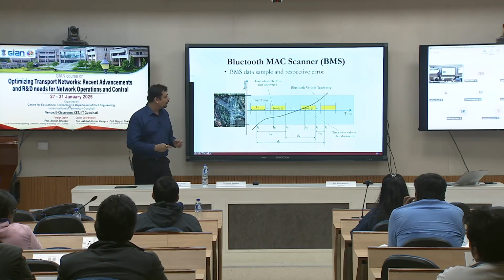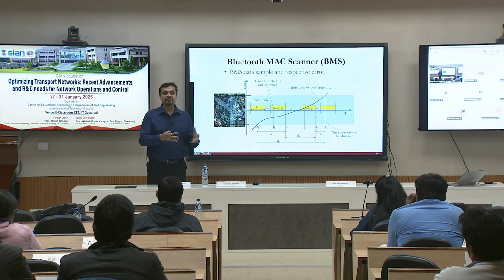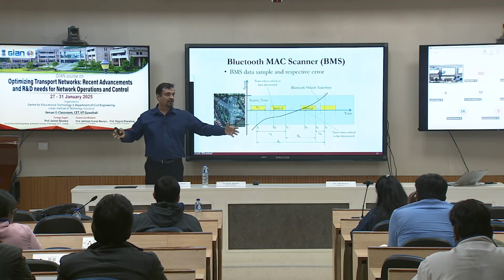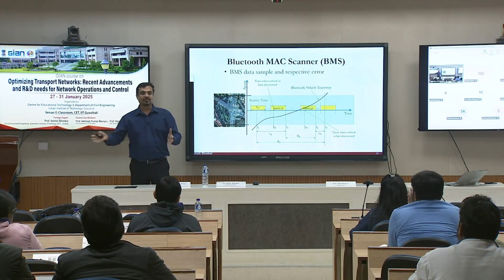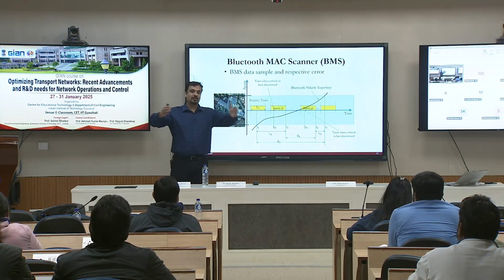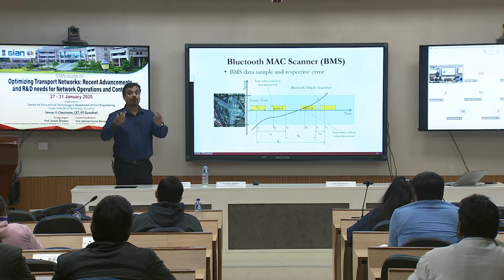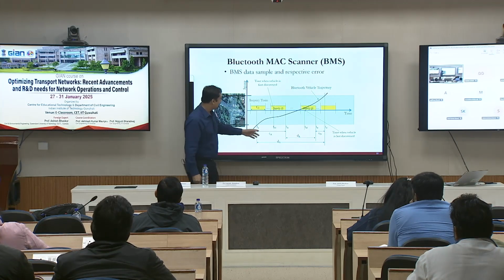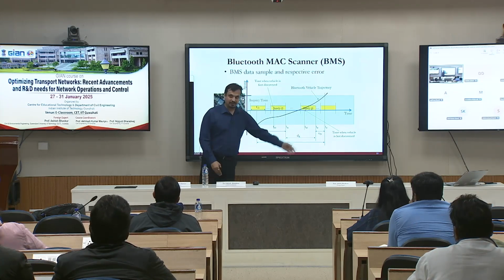Generally, you want to have at least 5 seconds for the device to be in the scan zone. If I'm going to put this on a motorway which has a speed limit of 100 kilometers per hour, I'm going to make a scan zone of 250 meters. On the arterials where I have a speed limit of 60, I'm happy with 100 meters. So you increase your scan zone based on the speed limit of the road, because you want to observe them. But yes, if the speed is high and you only observe once, the duration will be 0 for that guy. Only one observation. Then you have higher error from that angle.